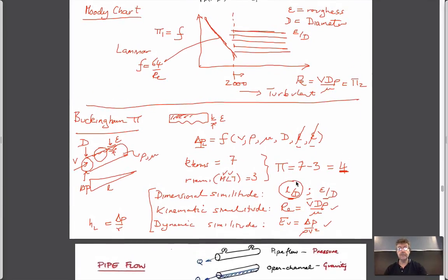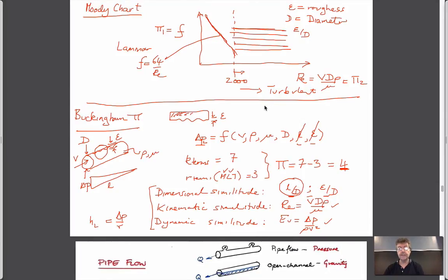And so if we want to be able to, I know it's getting a bit crowded here, we want to get the head loss terms. It's going to be a function of the length of pipe divided by its diameter. It's going to be a term which is a friction factor, and it's a term which is the inertial head, if you like, v squared over 2g. And so what this is saying, this is basically the equivalent of HL. It's not the right units, obviously, but because this is units of length and this is unitless.